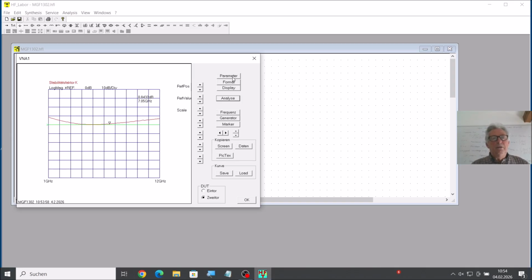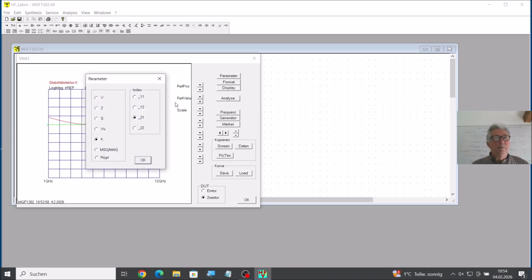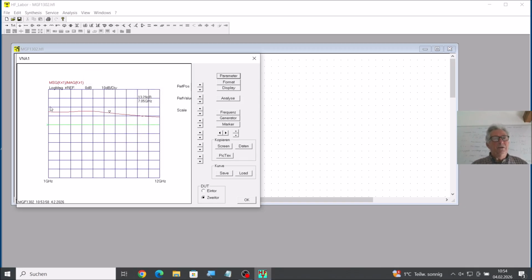But we will also see now, if I have a look at the parameter, the stable gain, maximum available gain, that now in this region the parameter is reduced and always the maximum available gain is calculated. So we see here now there is only a reduced maximum available gain to reach in the region of the former unstable transistor.